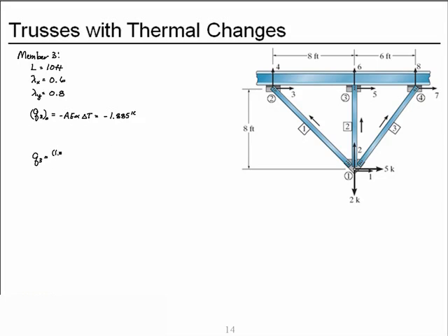And now the force in member 3. It's A E over L times minus lambda x, minus lambda y, lambda x, lambda y.